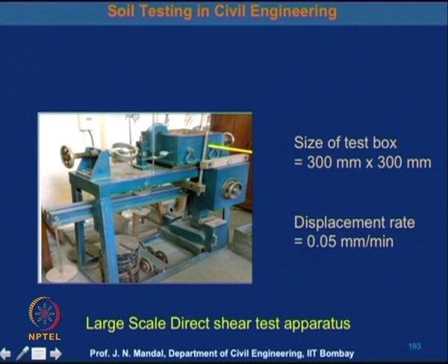In the large scale direct shear test, this is your shear box, which is about 300 millimeter by 300 millimeter. This is the size, and the displacement rate is about 0.05 millimeter per minute.